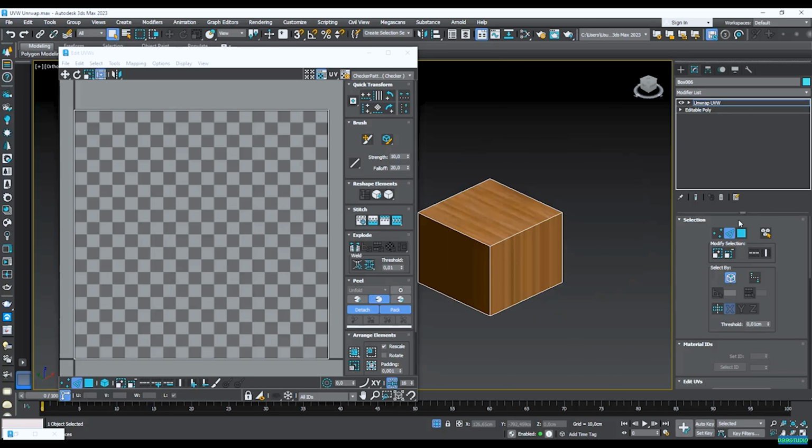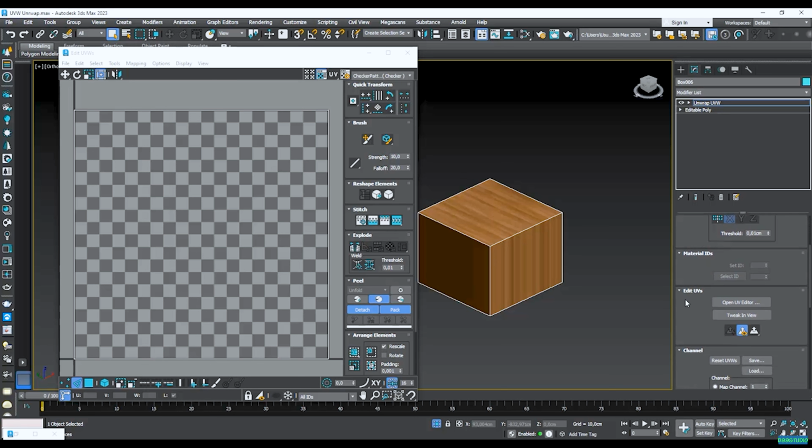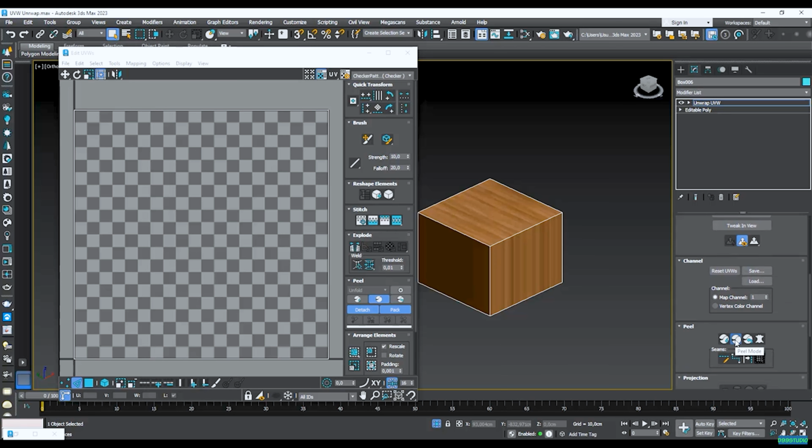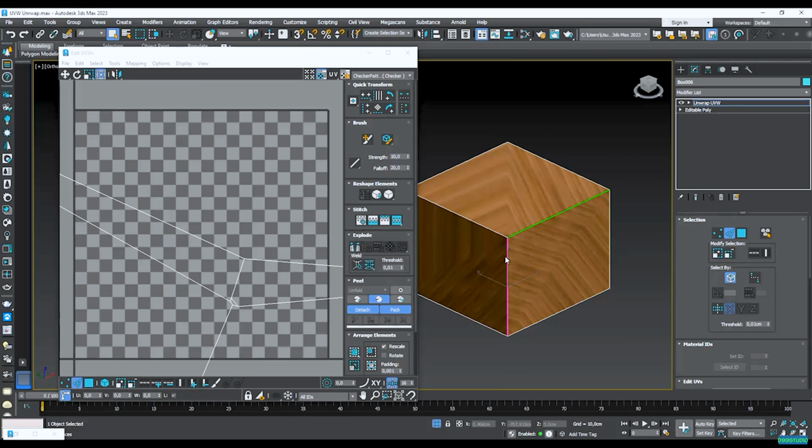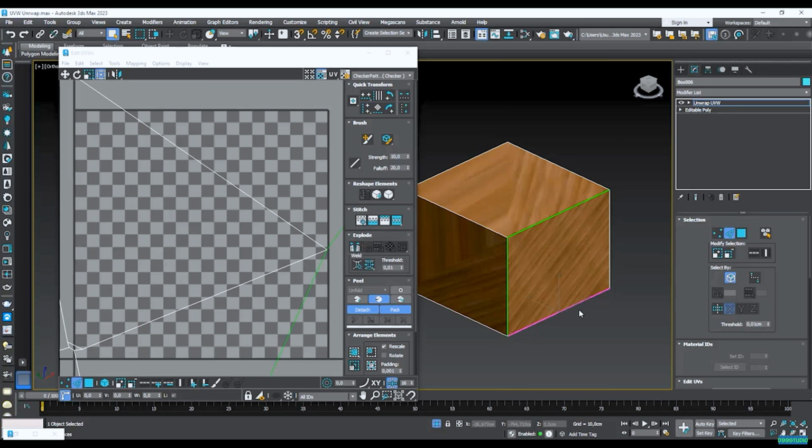And just before we get started, I must say that once we select one of the seams, we can't actually go back, not even with Ctrl Z. So this is the downside from using the peel mode. But as we move along, we're going to see several methods that we can use with it. For the moment, I'm going to start cutting this geometry. So I'm going to select this side here, then this side over here, and keep in mind that you don't have to press the Ctrl key. I'm just cutting this geometry through.